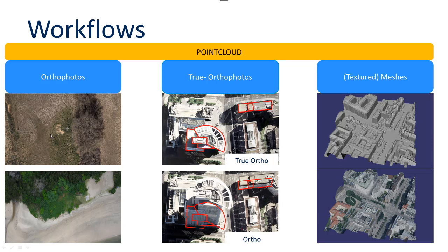The orthophoto production is a very classic standard production line where typically you have a digital terrain model. Then we have aerial images that will be singly georeferenced. So if I have 100 aerial images, then I will get 100 orthophotos. Then these orthophotos have been generated with a correct terrain model, and then we stitch them together. So in this case, through seam lines, the orthophotos will be merged together to a seamless mosaic, which is then